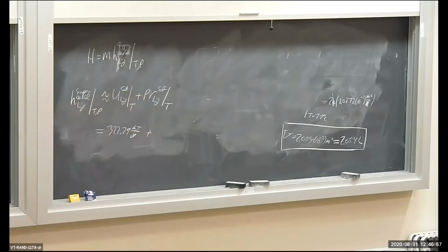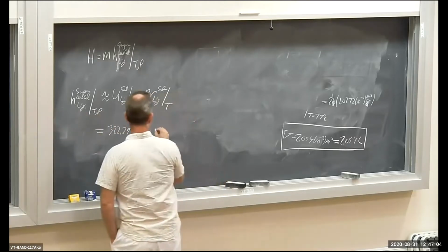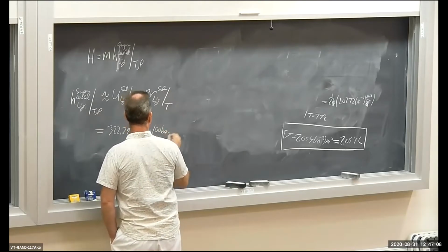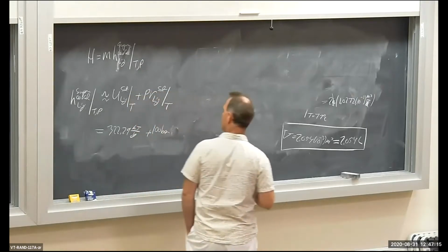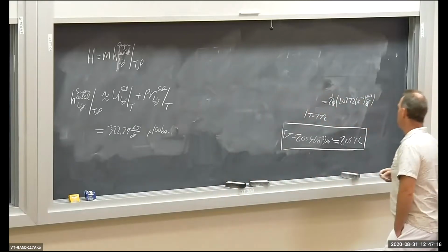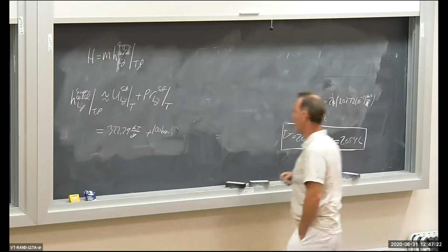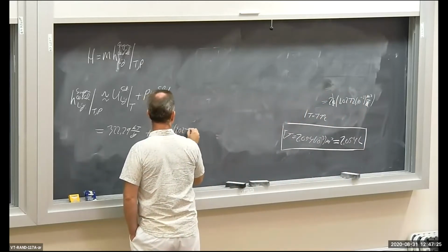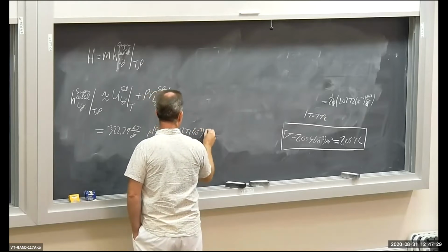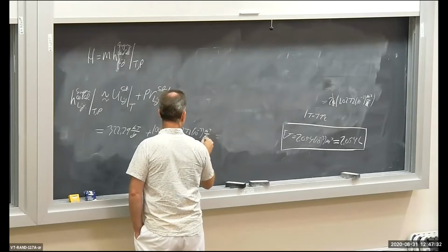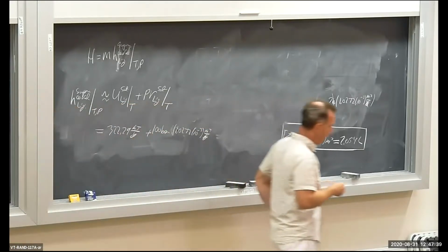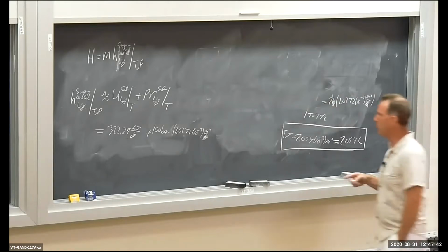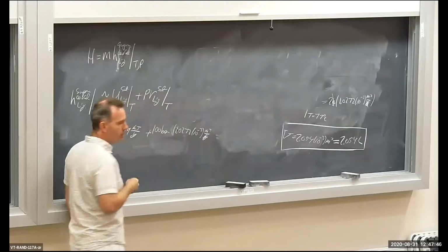322.29 kilojoules per kilogram, so that's the first term there. Pressure is 100 bar. And then specific volume of the saturated liquid, 1.0272, 10 to the minus 3 cubic meters per kilogram. Okay? Now we got some unit stuff to work on here. This is kilojoules per kilogram, and I got bar, meter cubed per kilogram in this term. I need to convert this into kilojoules.